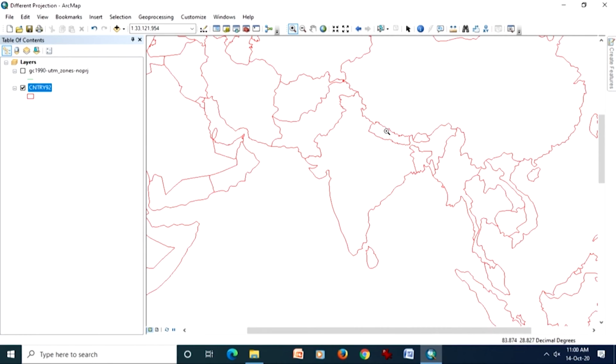So once it has been created, it's not a big issue. You can assign no data value as no color, and just remember, whenever you encounter no data value, assign no color. So it will mix with the background, you won't see it, and everything will be alright. After georeferencing of raster data also, it would create no data.